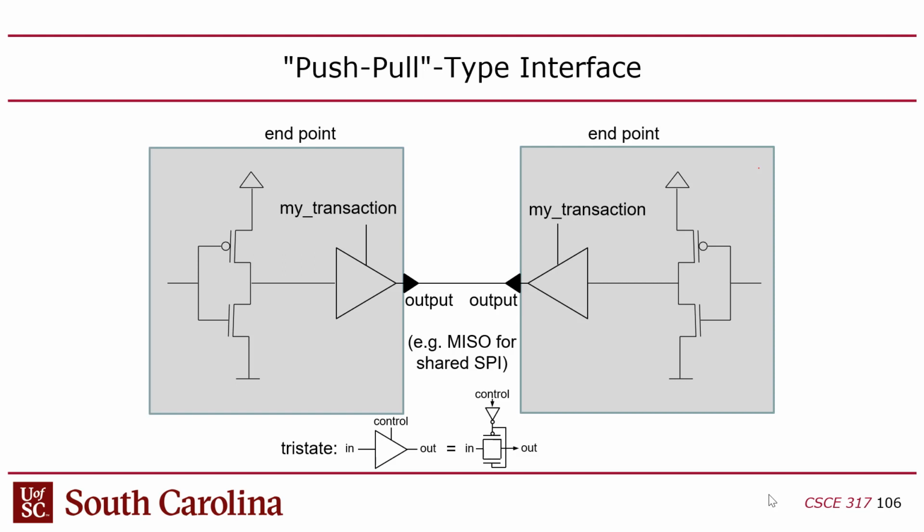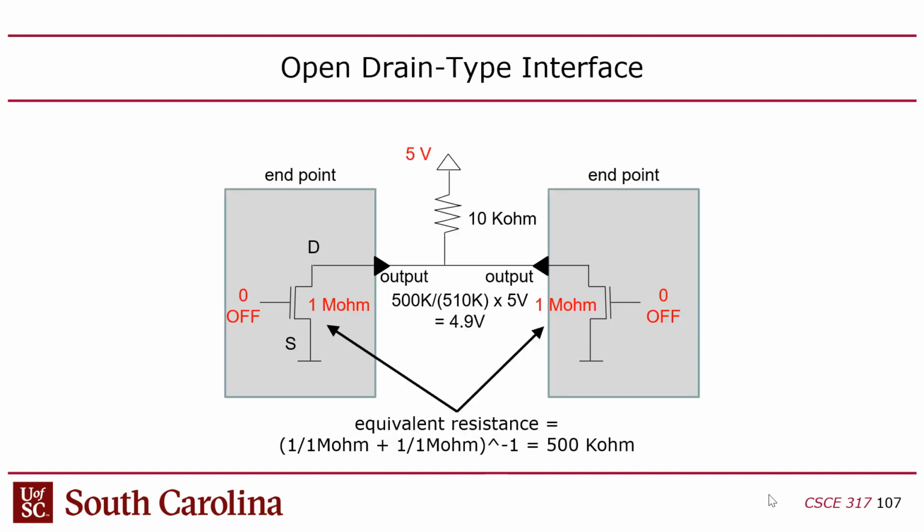So if you've got tri-state buffers, why would we want open drain? Well, tri-state buffers still have the disadvantage that if you screw up, you can cause a catastrophic failure, if the tri-state buffers aren't all synced up properly, like if 2 of them try to drive the wire at once. So open drain is just safer. It's a safer way to go for multi-master buses.